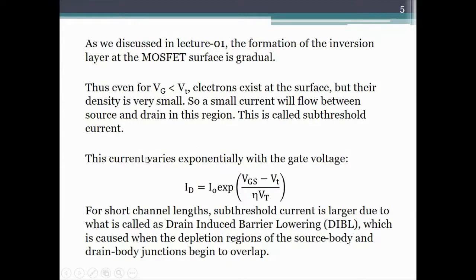It turns out that the current below threshold varies exponentially with the gate voltage. I will not derive this. In fact, this behavior is somewhat like a bipolar transistor. In a bipolar transistor, the collector current varies exponentially with the base-emitter voltage. Here, the drain current varies exponentially with the gate-source voltage. If one goes deep into the physics of the MOSFET as well as the bipolar, one would find that the reason for this exponential is in fact the same in both transistors. But we will not look at this. Just be aware that in the subthreshold region, the drain current varies exponentially with the gate-source voltage.